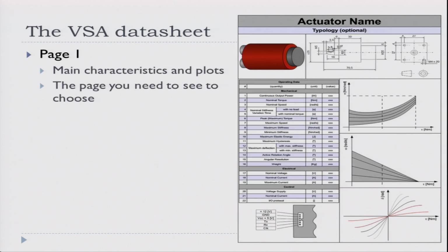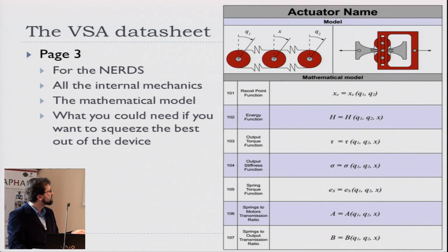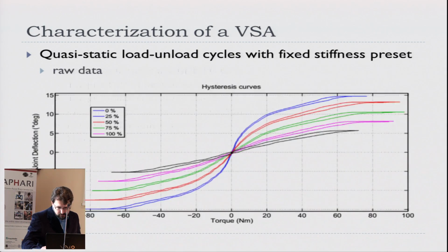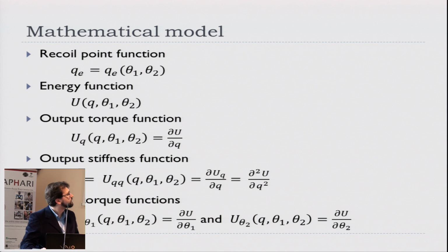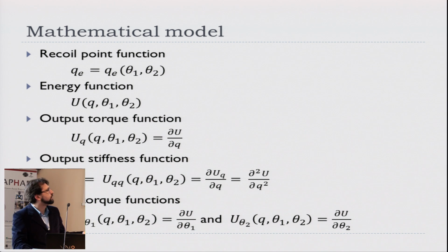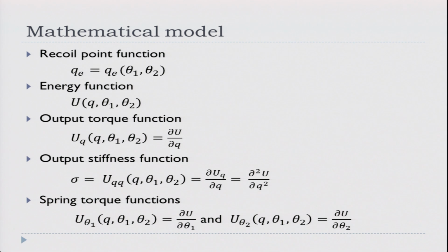For example, sorry, let's go back a little. If you want to do a very precise control, you probably have to compensate for these torques here on the motors. In our actuators, we do it with the integral part, which is enough for many applications, not for everything.